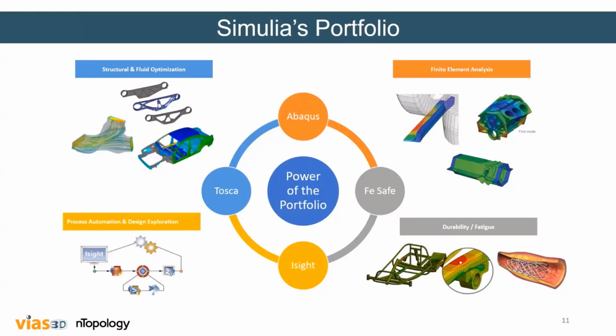And once you get the response surface function, then it becomes more like solving an algebraic equation, which is very fast, and there are still some checks and balances, of course, we have to do. And then it's almost a representative of your FEA model. So you change the parameter and still get the output of interest with fidelity using an algebraic equation. Then if you're working with a Monte Carlo sort of simulation or optimization where you need to run many samples, then the efficiency increases. Going to the next one.